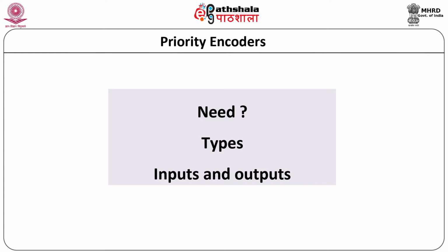Standard encoders generate the wrong output code when there is more than one input present at logic 1. This is one of the major disadvantages of the linear encoders. One of the simplest ways to overcome this problem is to prioritize the inputs. If there are more than one input at logic 1, then actual code corresponding to highest designated priority is produced, and all other inputs with lower priority will be ignored. This type of encoder is known as priority encoder.